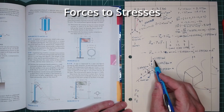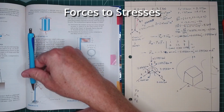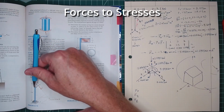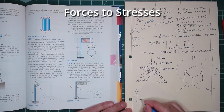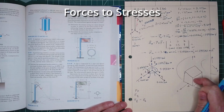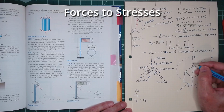This force is acting downward, and it's acting in an axial direction of our hollow tube. So this is really going to create an axial stress, and we'll call that just sigma z. And how is that going to be acting on our stress cube here? Well, it's going to be acting down on this top surface, and that's going to be our sigma z. Now, don't get confused.